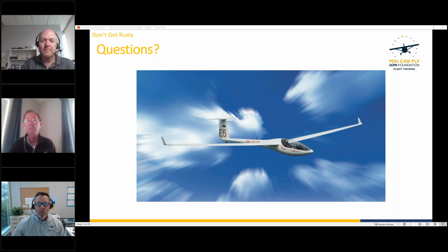Sure. One of the viewers is planning to get a commercial ticket in both airplanes and gliders. Do you have a recommendation as to which order they should do that? I started out in airplanes and went to gliders later, and I tell everybody that if I had the choice, I would have started in gliders. Because you just get a much better sense of what it is to fly, and a much better sense of the energy system, of the exchange of kinetic and potential energy, and energy management becomes much more tuned. One of the things that getting a glider rating will do is make you a better airplane pilot.